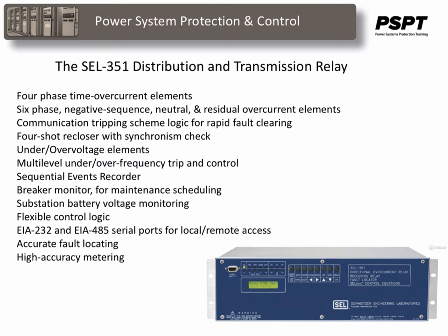It also has complete high accuracy metering elements, not requiring the use of external meters. Now, these aren't necessarily used for billing purposes, but certainly for control and for monitoring for the actual supplier. It gives you the accurate metering that's required. This relay is also extremely flexible, and you have a choice of amperages that you can feed into it. You can have 5 amps or 1 amp for the phase current inputs, or 5 amp, 1 amp, or 0.05 amp for the neutral current input.